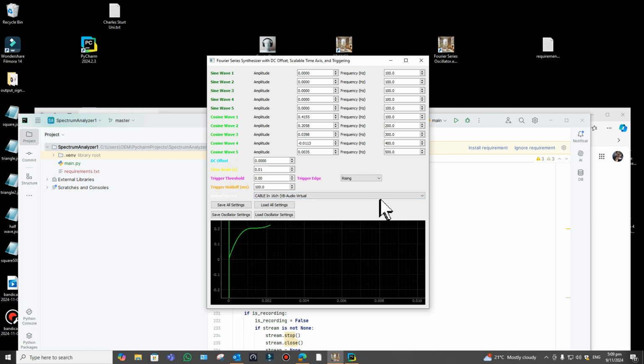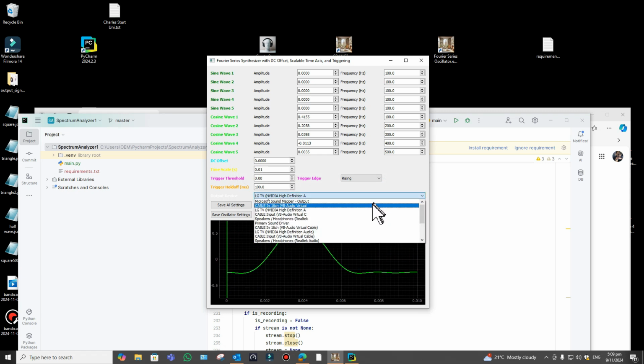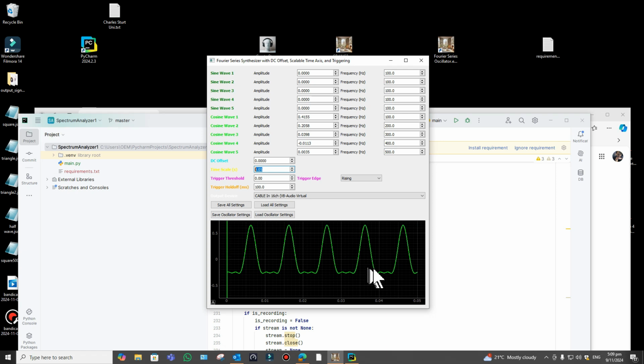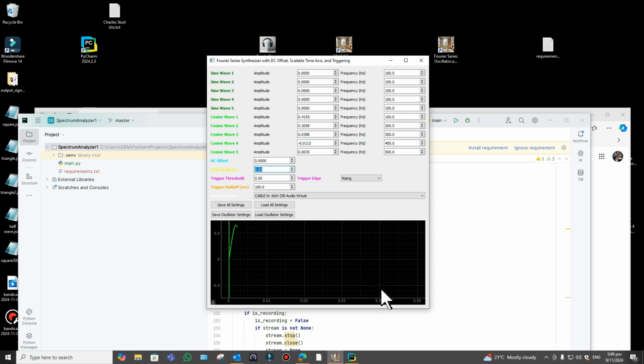Let's look at another one. Another triangular one, but this time again I need to zoom in. It doesn't look like a triangular one there, does it? But it is. It's a triangle, and then nothing, and then a triangle, and then nothing. It goes flat, and then up, down. As long as it's a periodic function and it satisfies certain conditions, which in electrical engineering it nearly always does, most of our waveforms are continuous. They don't have funny things in them. Then it should be able to get a Fourier series, but it must be periodic with a defined period.